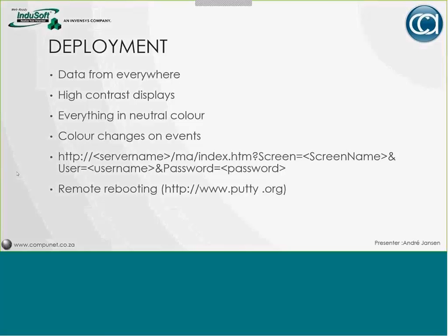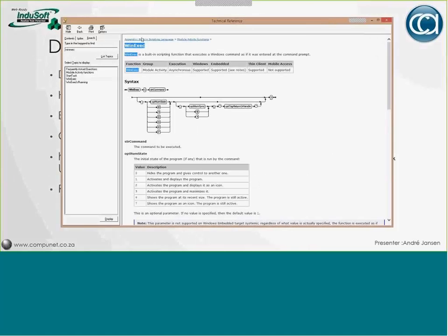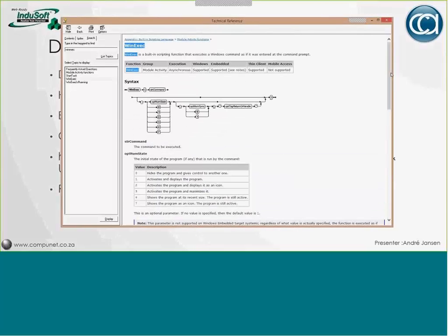By using the ability of InduSoft Web Studio to execute command line scripts with a WinExec function, we were able to execute Windows command line scripting. Here's the help file for the WinExec function that runs directly out of InduSoft and allows you to execute Windows command line programs or other Windows programs.